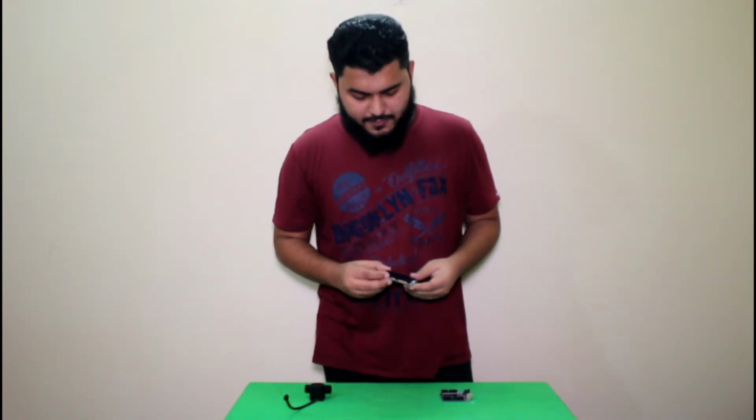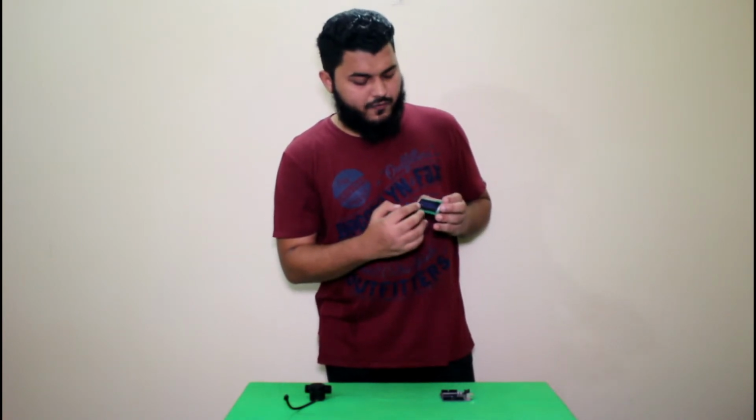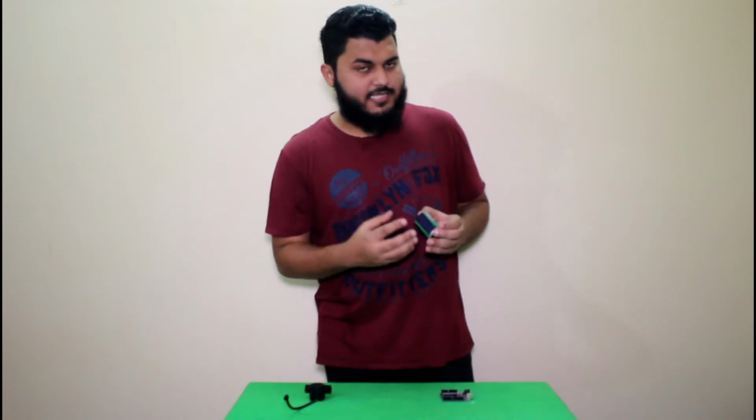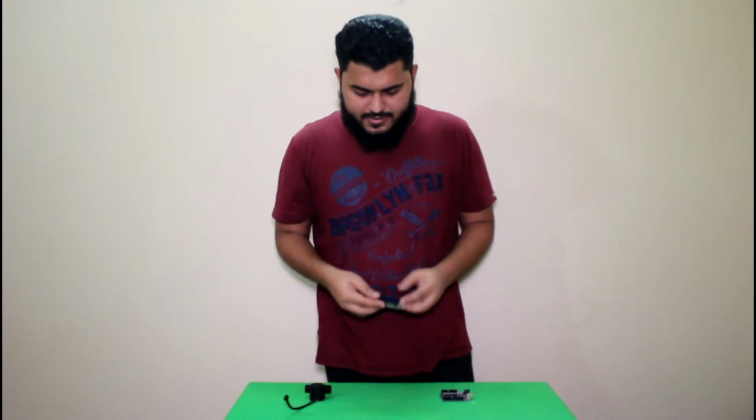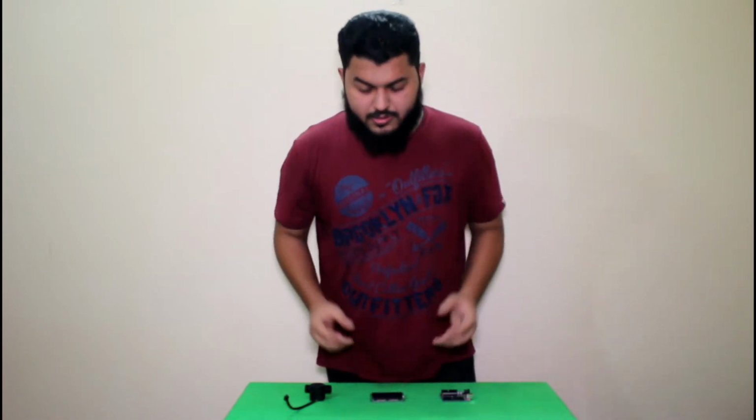And lastly, we have used an LCD display. It is a 2-line display with 16 characters. We can show 2 lines of strings in our LCD display. So we have used one line to show the 3 main aspects of the project, and the second line is for the speed of the flow sensor. And these 3 components are circuited together in a breadboard with some wires. That's all from me. Next we will discuss the whole circuit diagram.